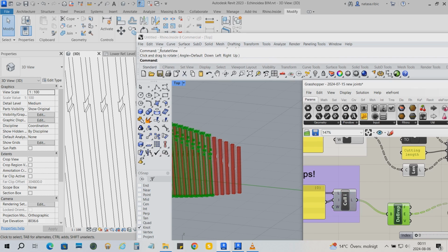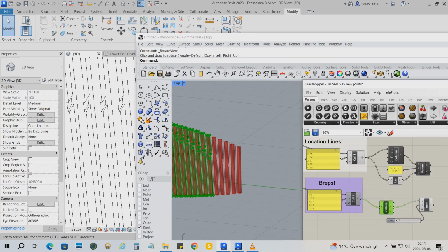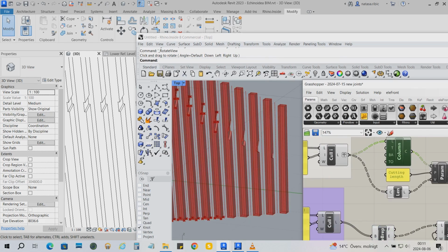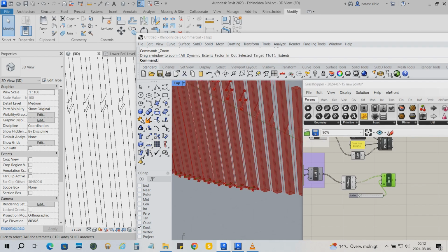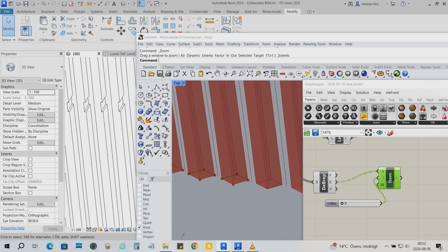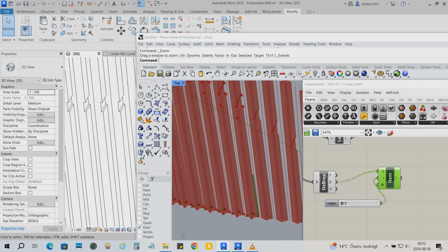and now I want to find, turn this off so this prep will be more visible, and I will even turn off this column, and let's see. This is the edge with index value 0, index number 0. I need this edge and this edge. Those two edges define the position of the joint. And then I need even this edge, because this edge together with this edge defines the angle of the joint. So let's find those edges.